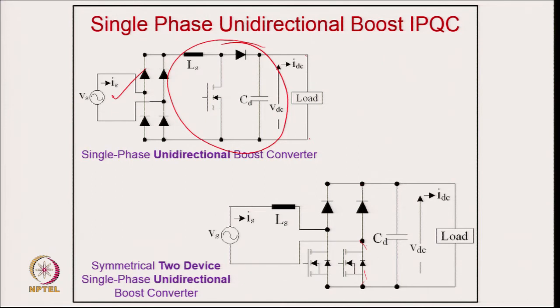The benefit of this is that the inductor is moved to the AC side. So, the design of the inductor becomes quite simple because it is an AC inductor now. Another benefit is the drop of one device here, because if current is flowing, it flows through 3 devices, here it is only flowing through 2 devices. So, you can say the converter losses are also reduced by approximately 50%. So, that is another benefit.